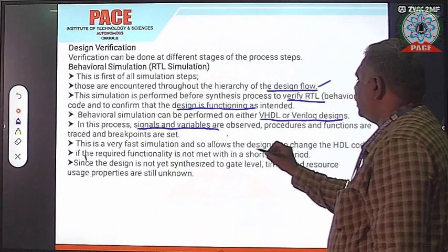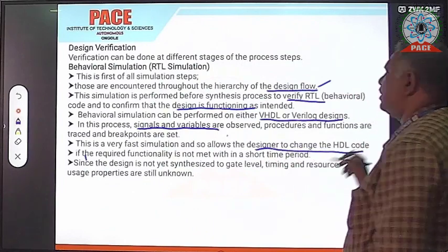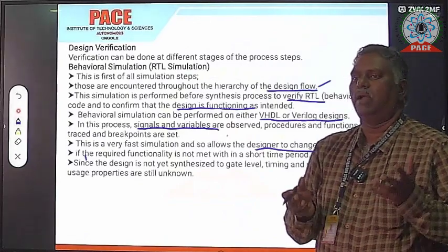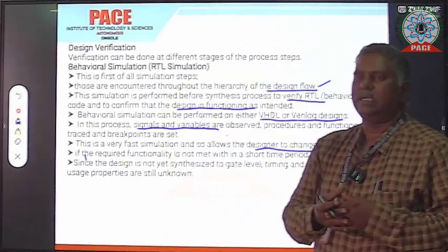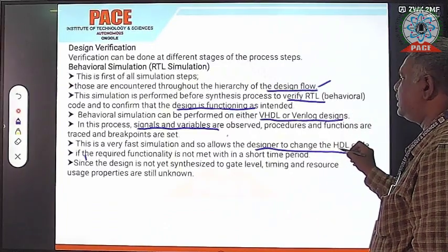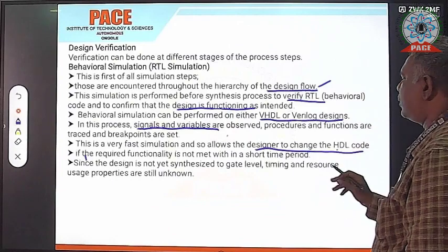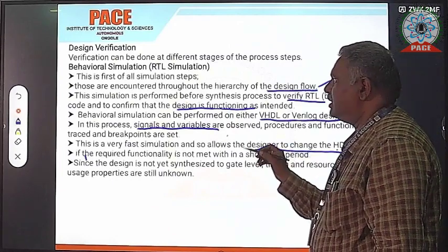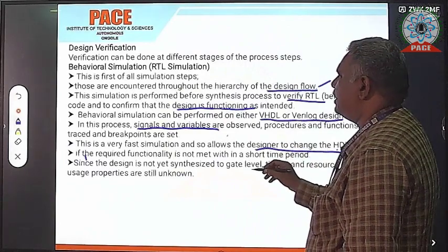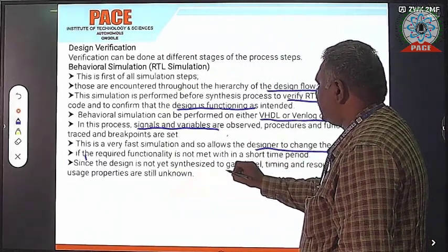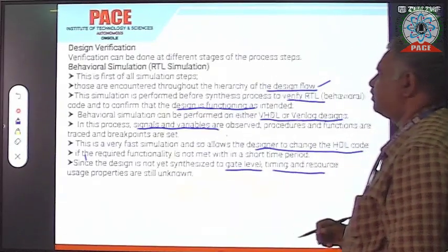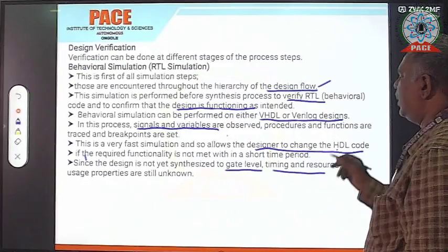If the written code is not accurate or not matching the design, the designer has to change the HDL code. So like this we are going to verify. This is called behavioral simulation, and another is gate level, or timing and resources. It is going to verify the timing and resources in this design verification.